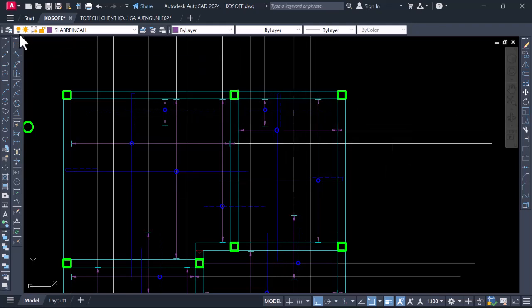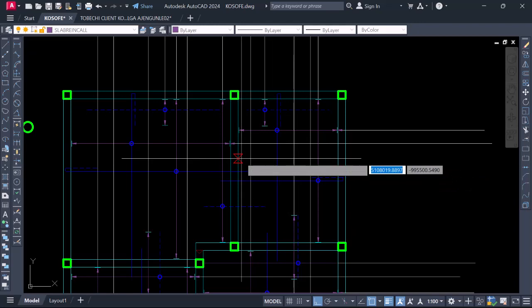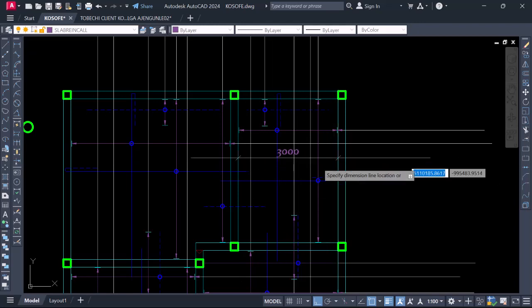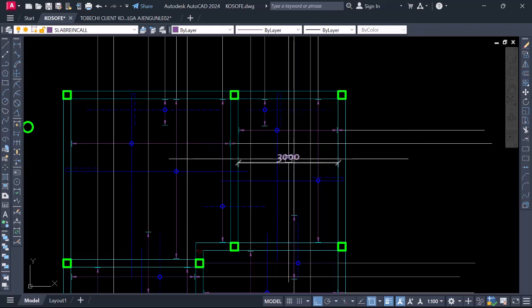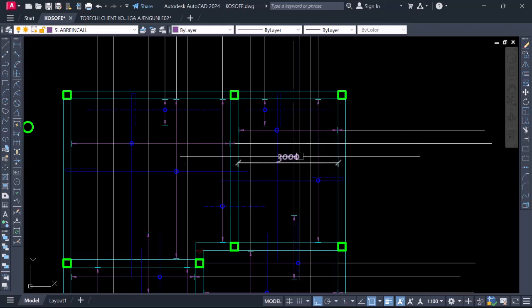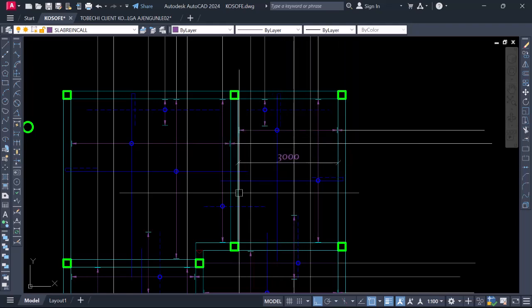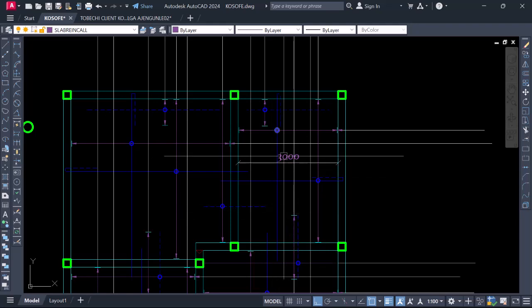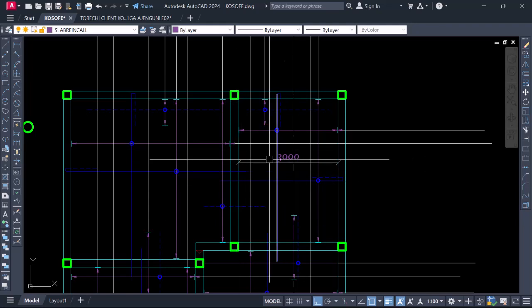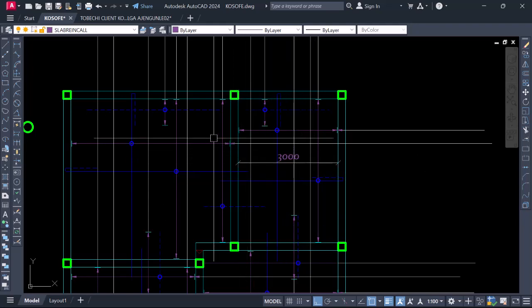So in doing that, by calculating this, we have the span like we all did. This is 3 meters, so we're going to divide. The formula goes by dividing this 3 meters by the spacing. For the reinforcement I will be going with 12 mm reinforcement, and my spacing will be 20 cm. You can go with 200 mm, so we'll go with 200 mm.